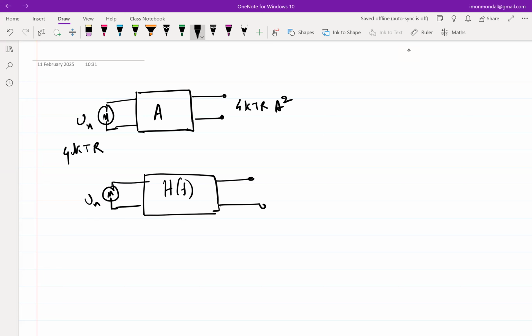Phase gives you delay. Now, when you are dealing with noise, will it make any difference if you observe a signal now or you observe a delayed version of it? Rather, let me correct myself. When you're dealing with noise, will it make any difference if you observe the noise output now or after some time? When I say any difference, I mean difference in the power spectral density of the noise. You will not get any, right? Because it's totally uncorrelated stuff, right?